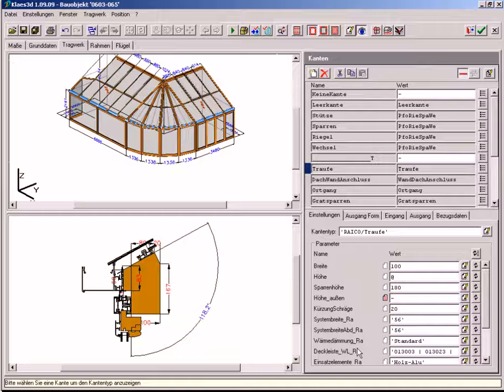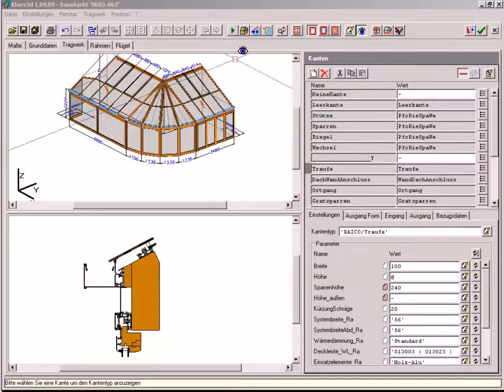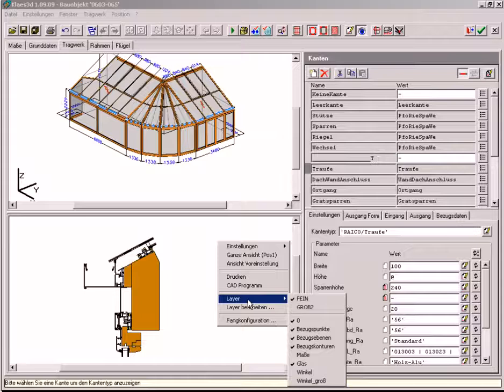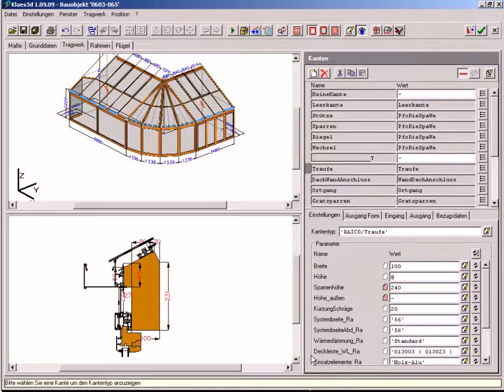The cut provides optional detailed information like the purlin height, special measurements, or the internal angle of a wall plate, for example. The defined parameter list of the section being viewed allows constructive changes within the section type to be made. Any change of dimension to any plane automatically or parametrically changes all the settings in the entire construction.